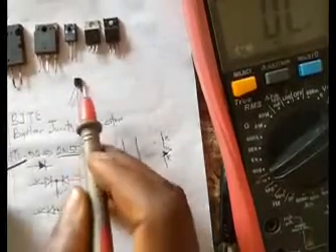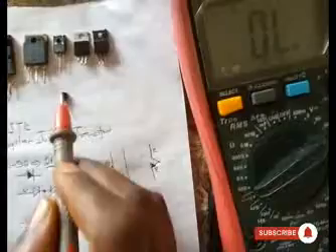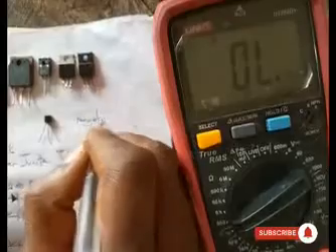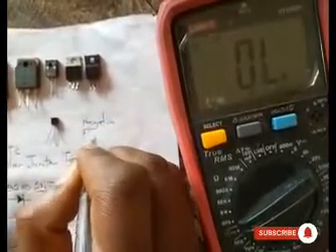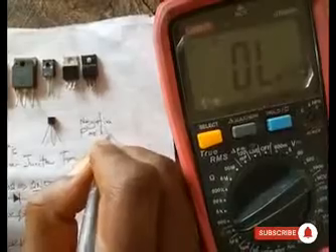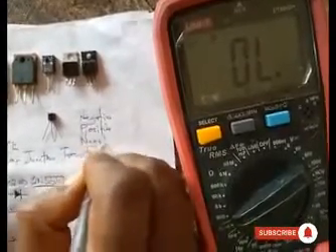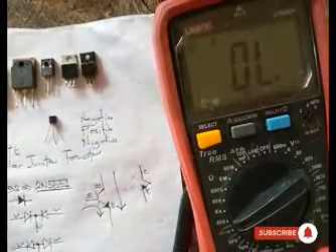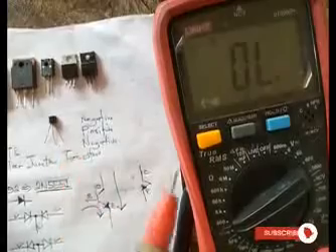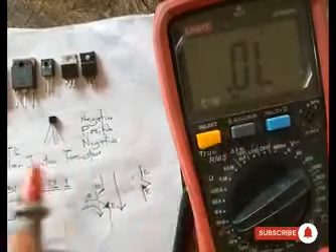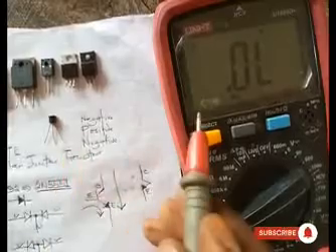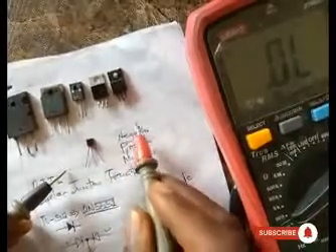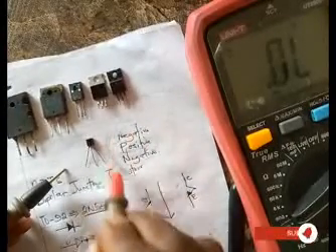Let me just give you this key. Already, we know that this is an NPN transistor. N means negative, P means positive, obviously, and the other N means what? Negative. So if it is an NPN transistor, it means that when we want to test with our multimeter, switch it back to your diode test, like I said. Your positive appeared once in the whole NPN naming.